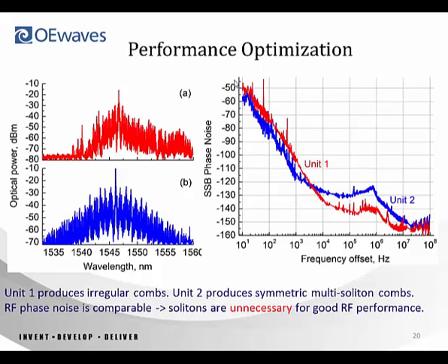made recently. First of all, as I mentioned, initially we used to work with very narrow frequency combs and generate proper RF signals. But then after observing the mode-locked comb, we decided that mode-locked combs definitely have much better low frequency phase noise. However, from build to build, because of the high density spectrum in the resonator, we observe some combs that look ugly, like this red one. It has many lines, and it definitely doesn't produce signals corresponding to pulses within the cavity.